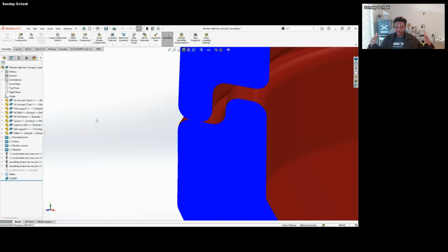Clearance comes into play where this should give a certain space so they can go together, and that's where you have your clearance. So you need a certain gap between these devices so they can go together. We have interference, where you need to decide at what dimension these two pieces interfere with each other, that they are touching, they're going between each other. And this is mostly used in cases where you have to use flexible material, so once that flexible part goes in, it's tight there and doesn't come out.